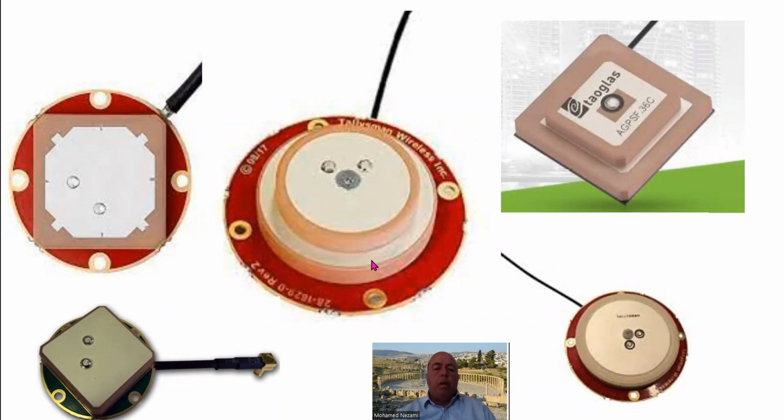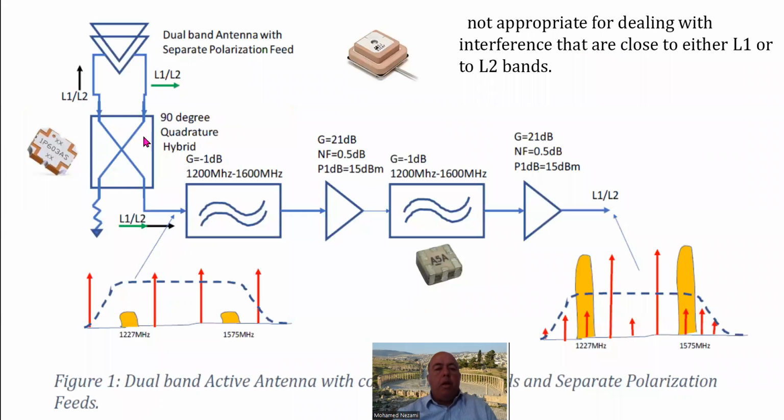And this is the lower L2 band, which has a smaller bandwidth and wavelength, and as you can see in the bottom, here's the ceramic. The feed for this one, you can't see it because it stops beneath this one here. So some of them are single point feed like this, although most of them are like this, where we take the vertical and horizontal and then combine them in a 90-degree hybrid, as I show in the vectors in here.